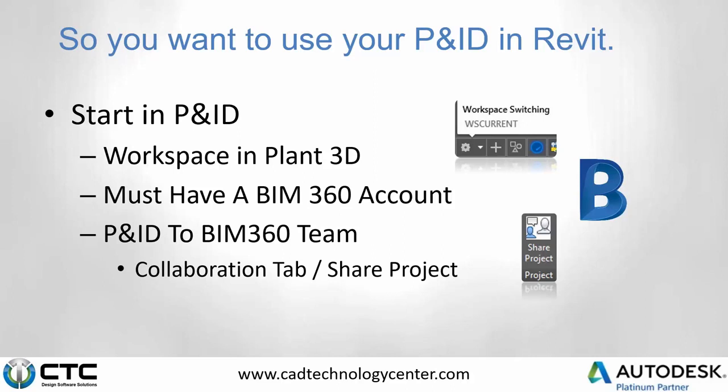The biggest thing you need to know about PID is that there is no standalone Autodesk application named AutoCAD PID. The PID application is a workspace change inside of Plant 3D. So if you're looking for your Autodesk PID in your AEC suite, it's located inside of Plant 3D, and then you would simply change the workspace in the lower right-hand corner to be PID and either PIP, ISA, or ISO. So you have a couple different standards there you can pick from.